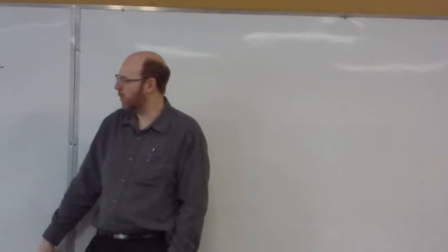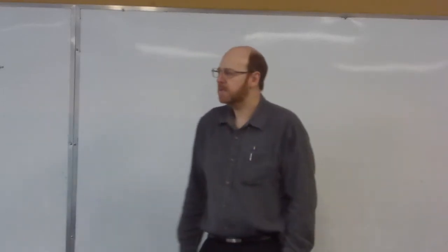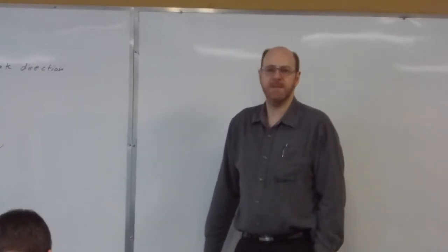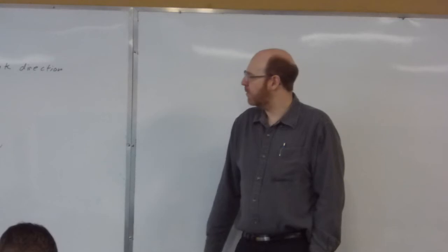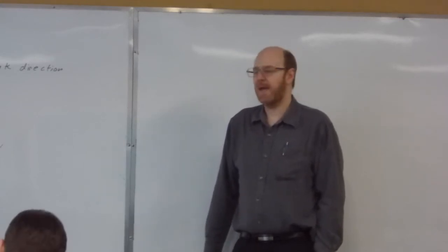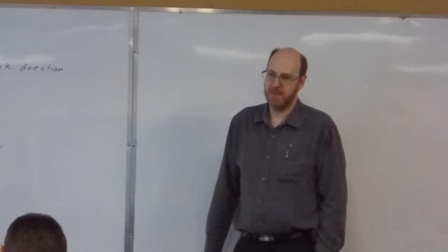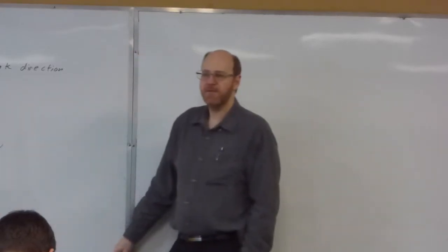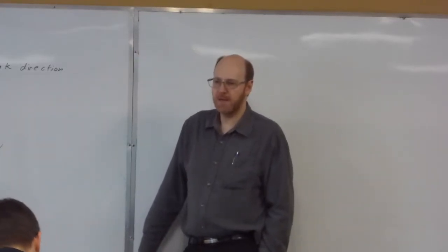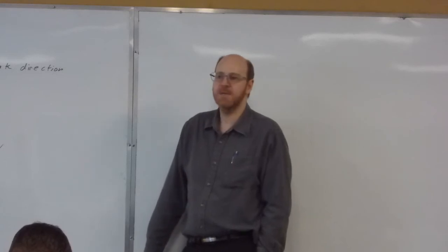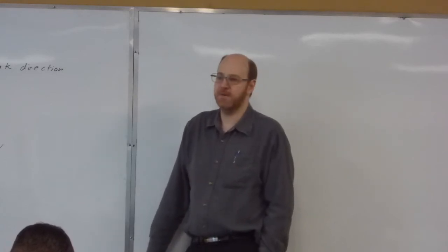Now, slip critical with our bolts is a little bit different because with slip critical, we technically define this as a serviceability limit state rather than an ultimate limit state. So what that means is if it does happen to slip, then the building's not working as intended, but it's not a collapse mechanism. Whereas with the previous calculations, the bolt shear, right, if I exceed the allowable shear stress in the bolt and the bolt just snaps in half, we do potentially have a collapse mechanism, and potentially that could impact people's lives. So as a result, we have a significant safety factor involved with it.